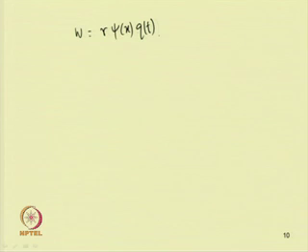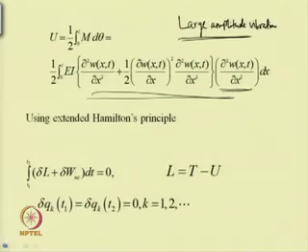By using this equation in kinetic energy, potential energy, and finally in the Hamilton principle, one can derive the temporal equation of motion by applying the Galerkin principle. The use of the Galerkin principle has been discussed in the last class. So, one can use that principle to derive the equation of motion.